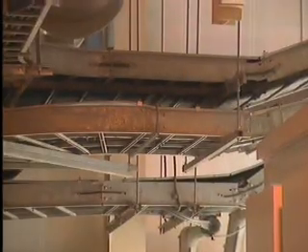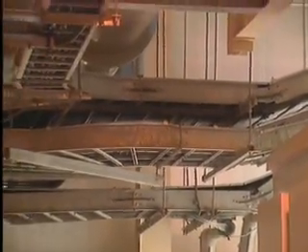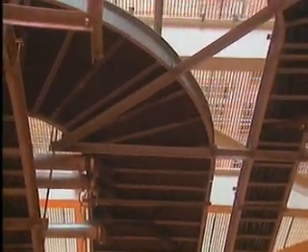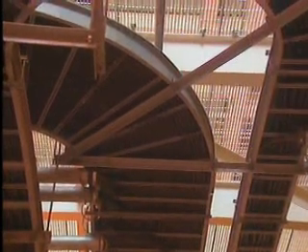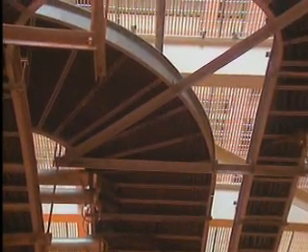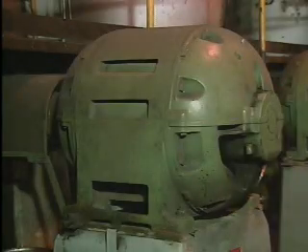Not all electrical hazards are visible. One hazard that's not visible is associated with induced voltage. For example, even if one of the wires in this cable tray is not connected to a source of voltage, it can still become energized. Current flowing in a nearby energized wire creates a magnetic field that can induce a voltage and cause current to flow in the disconnected wire.